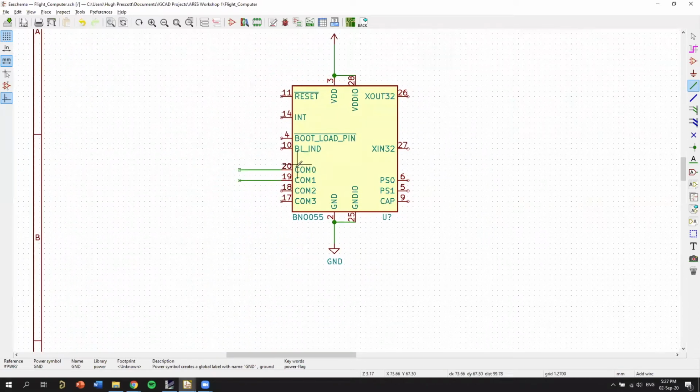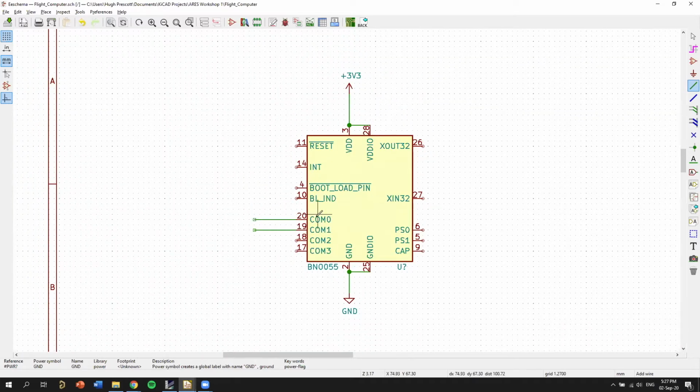That means on our I2C, when you're transmitting a sequence of bits, like 1 0 1 0 1 0, that's going to be transmitted as high low high low high low, and what we're telling it now is that the high is going to be at 3.3 volts.